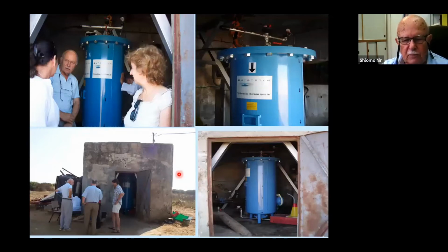We had quite a few experiments in the laboratory, including perchlorate removal, and of course we had modeling. So the pilot at the well intended to remove perchlorate started as sort of a prediction. Perchlorate is a large anion, ClO4 minus, and due to this, it hardly adsorbs to soil particles, but it does